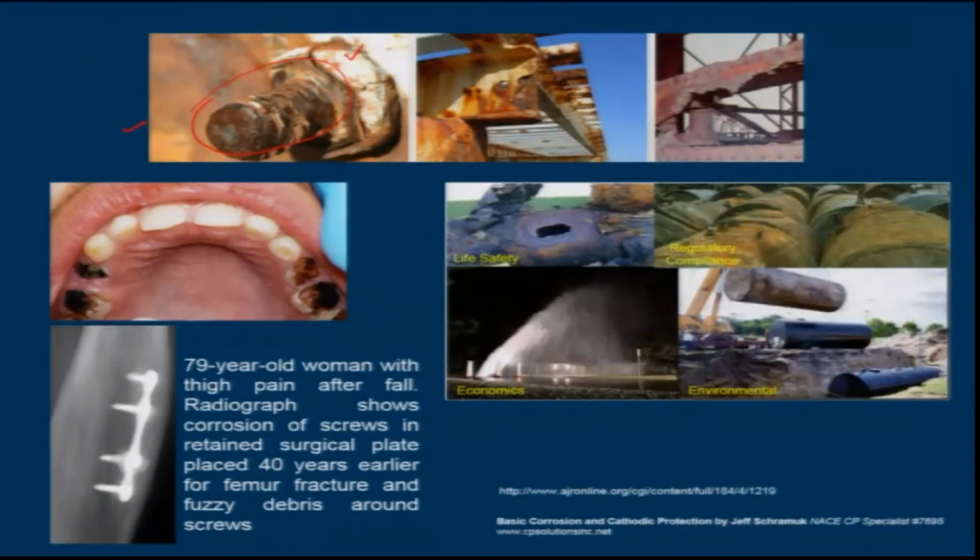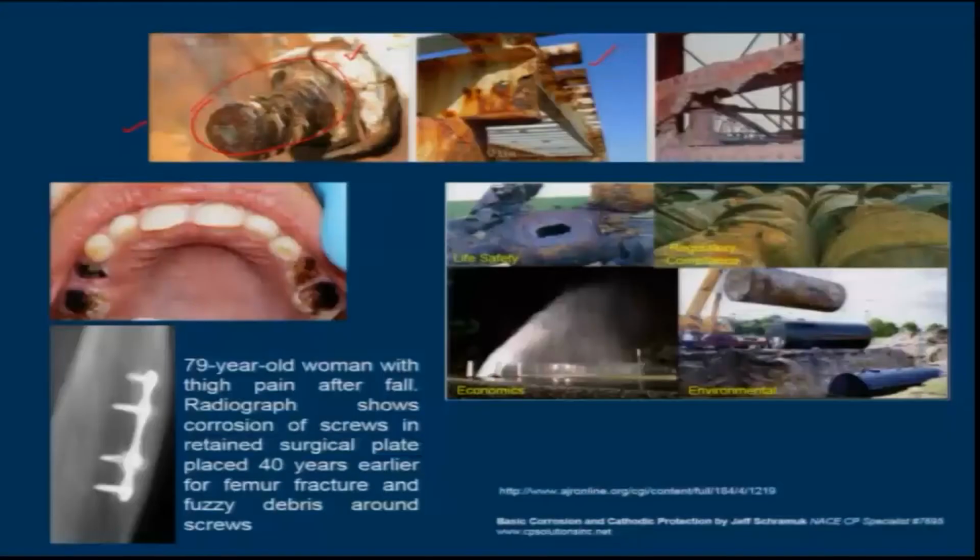Now, another commonly observed feature is overhead structures and beams, which are also heavily corroded. Corrosion, in most cases, comes with a different color, and in many cases you do not find any signature of corrosion, but it still happens, and those cases are more deadly than cases where you have a signature in the form of color change. Here you have the red rust which is forming, a typical feature of iron corrosion.